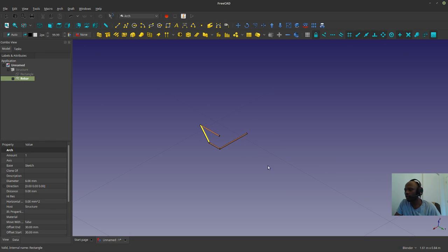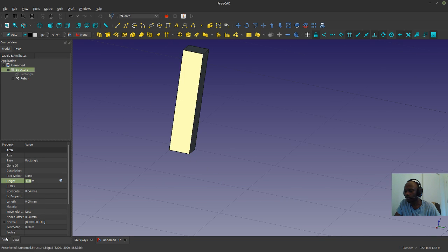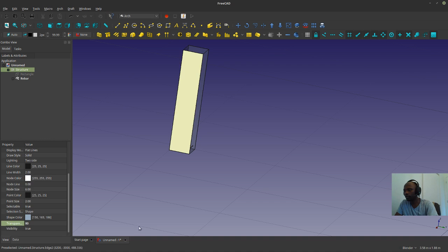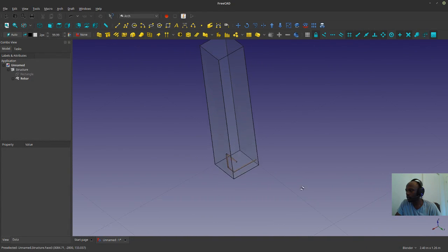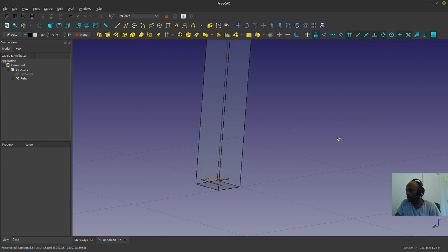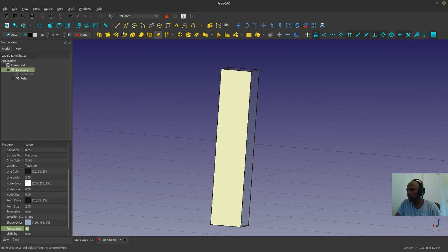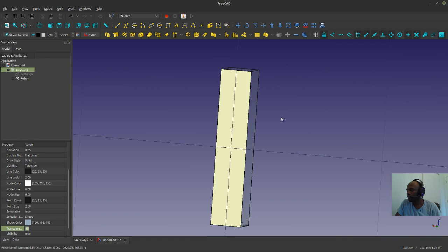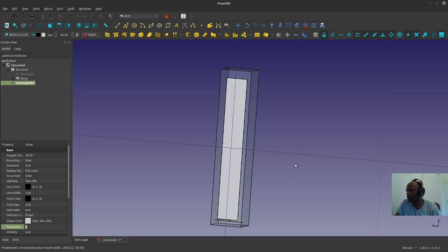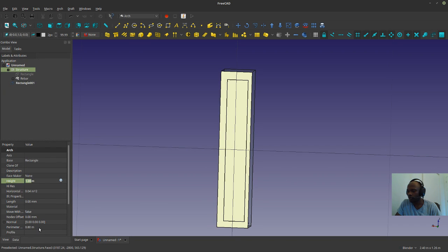So now, if that is the basics, let's try something else. I'm going to make this column slightly transparent, transparent 80, like that. If I do that, let's pretend that I have this face that I want to draw there, like this, and I want to put some rebar in this fashion, and then I'm gonna put some radius to this thing.